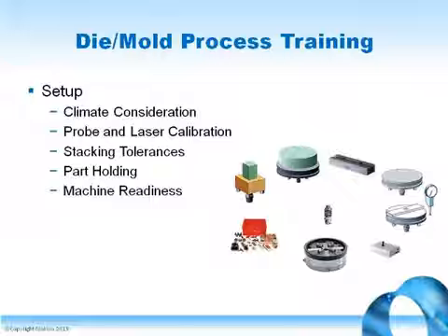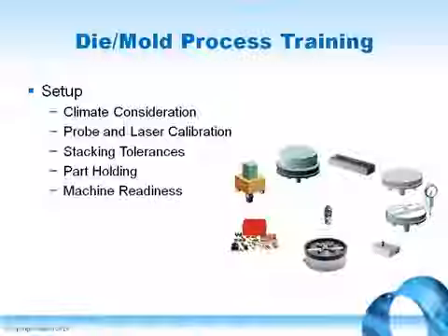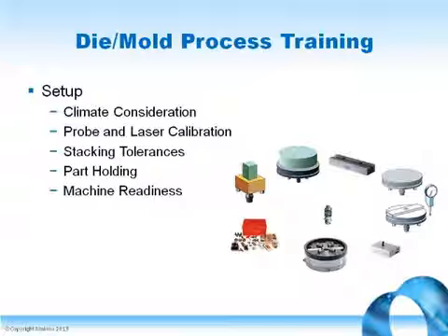Stacking tolerance is a combination of your cutter's runout tolerance, cutting edge grind tolerance, proper extension causing deflection, holder's runout tolerance, holder's cleanliness, current condition of holder, table accuracy, table cleanliness, flatness. Are you stoning out nicks and burrs from the table in part holding, or fixturing?